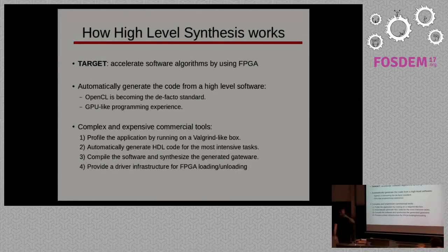These are very complex and expensive commercial tools in which you provide an application, the application gets profiled by a Valgrind-like machine or something similar, and the most computing-intensive tasks are identified, and there is an automatic generation of the FPGA code that covers these most intensive parts of the software.